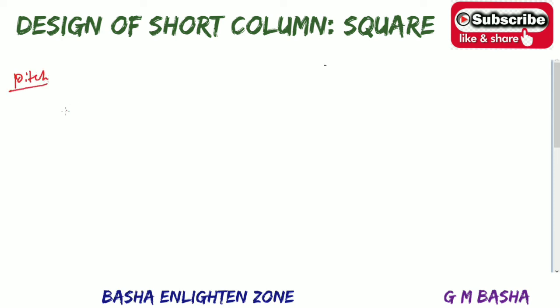For pitch, what are the conditions? The least lateral dimension of the column. Here there will be two column sizes; one is a square column, therefore I am taking the first one as 400 mm only. The second is 16 times the diameter of the longitudinal bar.